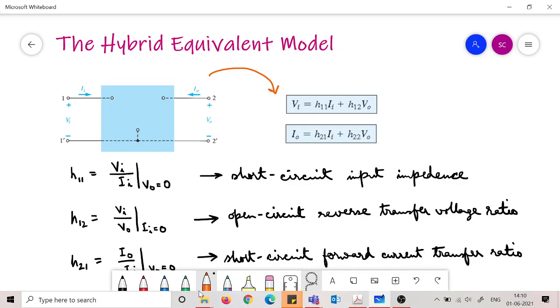I mean that whenever you have a 2-port system and you don't know what is inside, you only know the outside variables, the external variables: on the input side Vi and Ii, on the output side V0 and I0. These variables you can measure by employing a voltmeter and ammeter. So these variables are known and measurable.